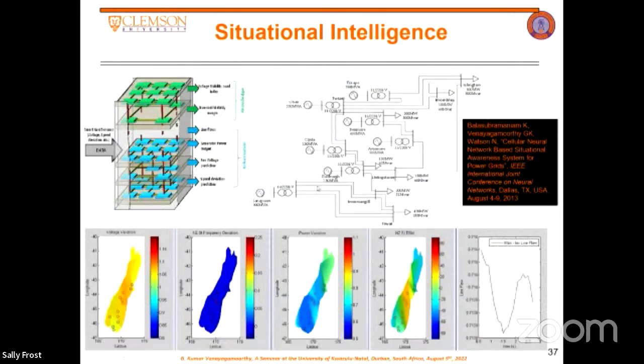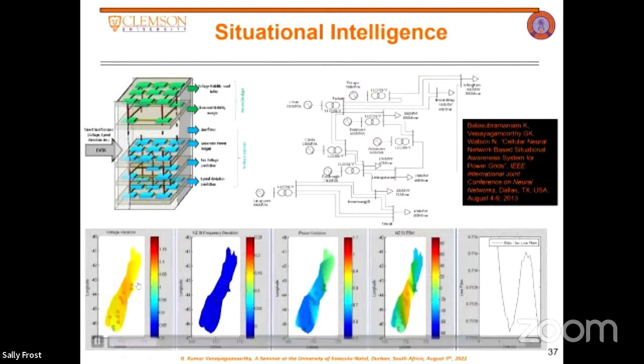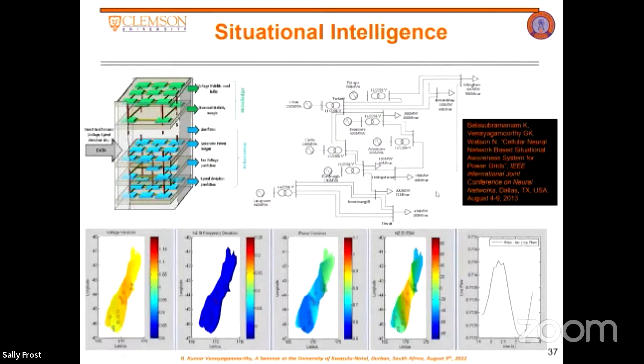And we're going to see how the CCN is able to predict all these different variables. Here we have the voltage variation across the island, the frequency variation across the island, the power of the different generators and buses, and the transient stability margin. And here is the line flow on one of the lines on this network. Right now it is 0.71 per unit, even though it's changing, but it's still 0.71. The fault is going to happen anytime now, and you're going to see how through the CCN we model all these different variables, dynamics happening on the grid.